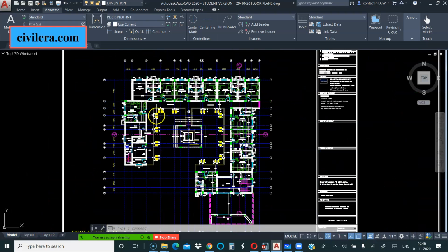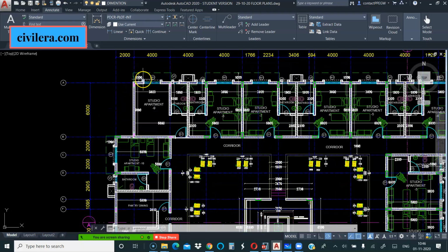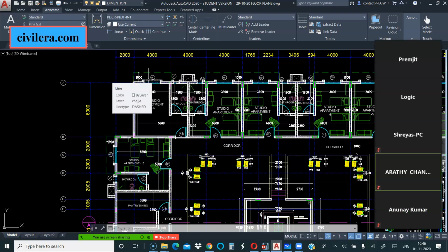Before doing all this, I would recommend to get a soil report, because sometimes the column numbers or the spacing of the columns and all that can be influenced by the type of the soil. So if you have a very poor soil, we might not want to have 6 meter spans and things like that. So based on that, we might have to have a different column spacing.